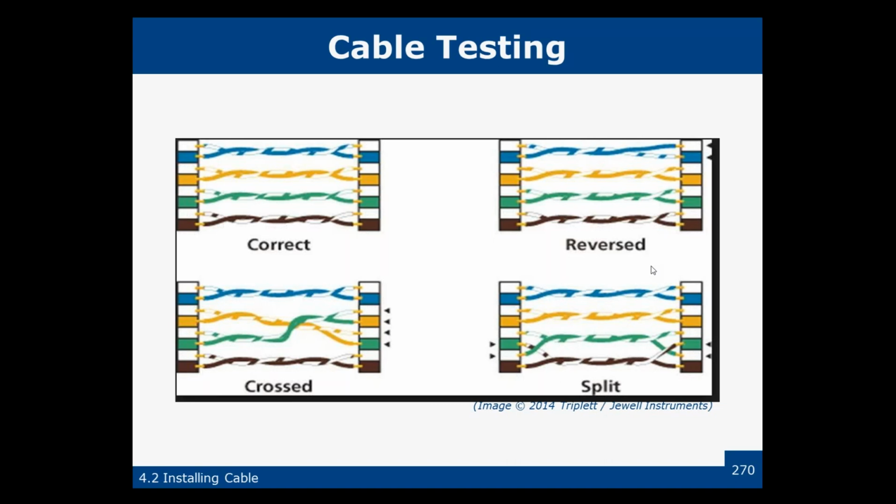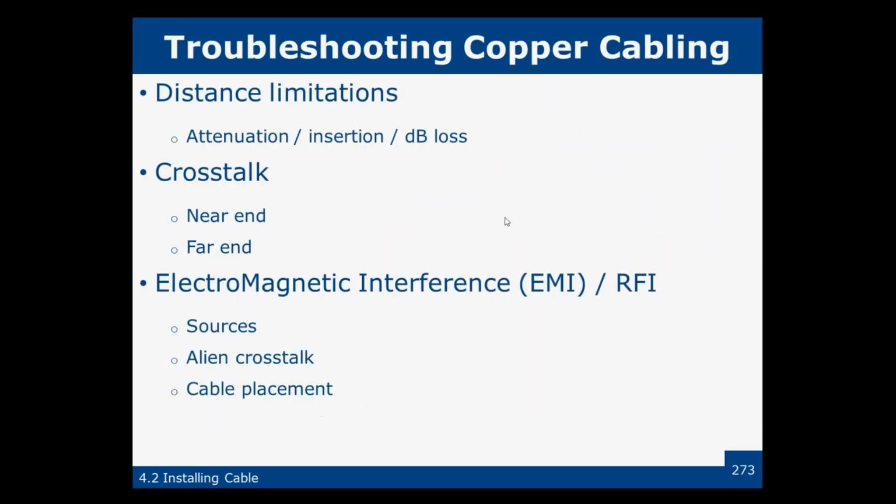How would you test for excessive attenuation in a network line? TDR, I guess. Right? Yeah, what we're going to have to do is inject a signal. TDR would do it. And that's here. We do attenuation, insertion, and see what kind of dB loss we have. And the TDR would tell us that also. The dB is decibel, and that's just what it's measured in.